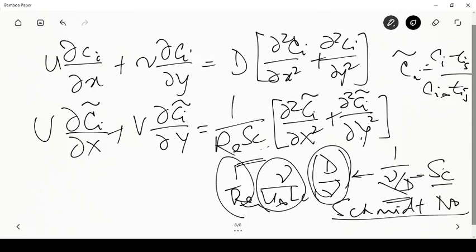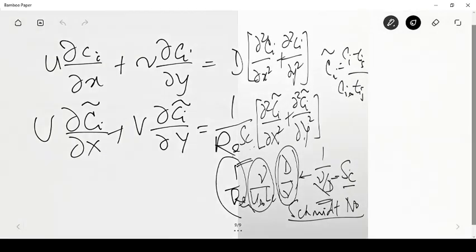So you see that the governing equations for transport of momentum, energy and any species have the same form, and if Schmidt number is 1 and there are no pressure gradients in the momentum equation, then all of these equations are exactly similar to each other, and with the same boundary conditions, and therefore their solutions would also be the same values. So that is what one understands by Reynolds analogy. So Osborne Reynolds looked at these equations and basically came up with what is called the Reynolds analogy.